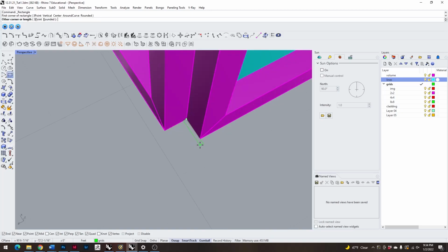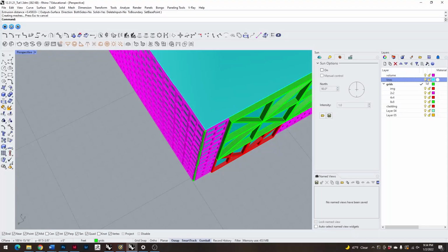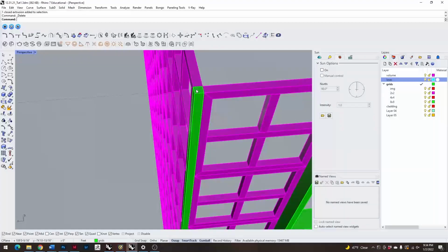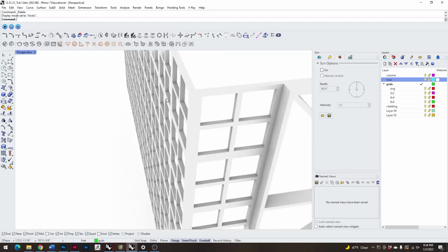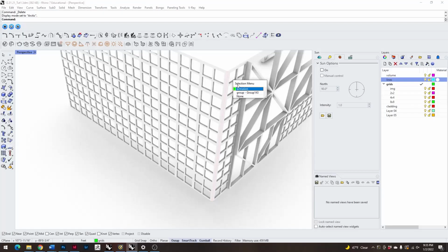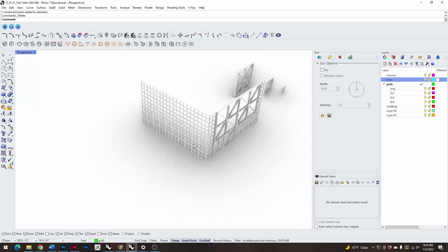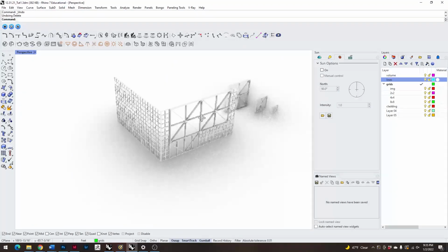I think here what I would recommend doing is making another rectangle and then extruding that rectangle, extrude with the extrude curve command vertically, just so that eventually, when you delete this volume and are left with just your grid, and I'll switch to a different view mode, that corner is a controlled condition without this weird divot that makes the geometry inconsistent.